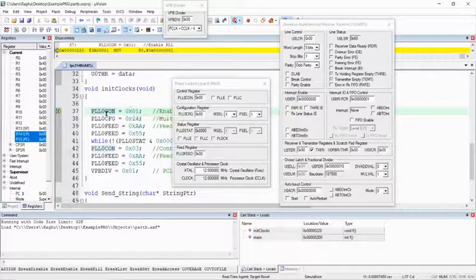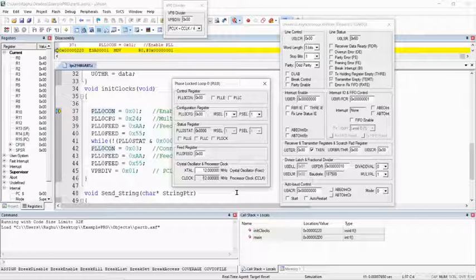These values are to convert my external frequency, 12, to 60 megahertz. So the external frequency is 12 megahertz, and the clock frequency is the same. Now I want to convert this clock frequency, which is the same as the phase frequency, into the processing clock frequency. So first I should convert this external frequency 12 into 60 megahertz. For that, these steps are used. I'll execute this.